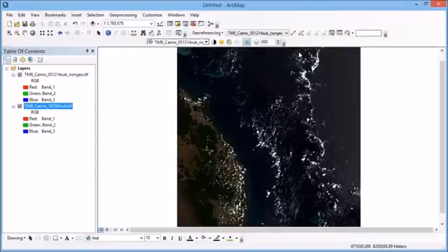Sometimes crop boundaries can also be highly changeable, so we don't want to pick those either. So we're looking for really dominant features in the environment that are not changing over the period of time that we've collected our data. So that might mean some major road intersections, railway crossings, that sort of thing. So we want to zoom into the image and find those control points.